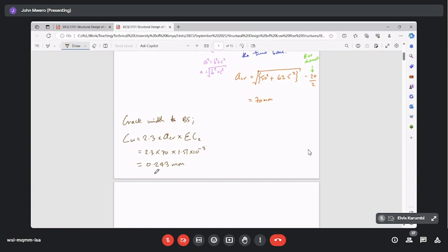The standards limit the size of these cracks depending on the purpose for which the concrete is made. I'll repeat. The standards for design of reinforced concrete structures put limits on how much crack size you can allow on a particular structure based on the purpose of that structure. So I'll give you two examples. If you're designing a water tank, a reinforced concrete water tank, which is where we came from, the previous topic, we did an overview of water tanks. So if you're designing a reinforced concrete water tank, now we know that concrete will always crack. Therefore, we need to check, after we've designed and put in the reinforcement, how much the crack is. And if it's not small, we need to change some parameters, which I'll talk about shortly.